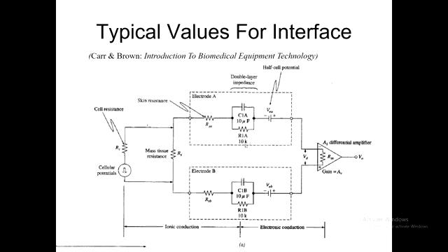In the electrode, this particular electrode is favoured to have 10 microfarads of capacitance, and that seems to me to be quite a lot for a small red dot electrode, but we'll go with it. 10K is a sensible shunt resistance to observe there. The half cell potential, as we've said before, is going to be between 0.2 and 0.3 volts for the silver chloride electrodes, and we'll have in the order of tens or hundreds of ohms for the skin resistance and the lead resistance.